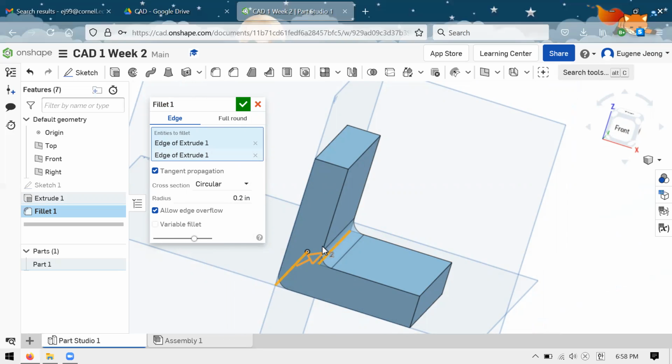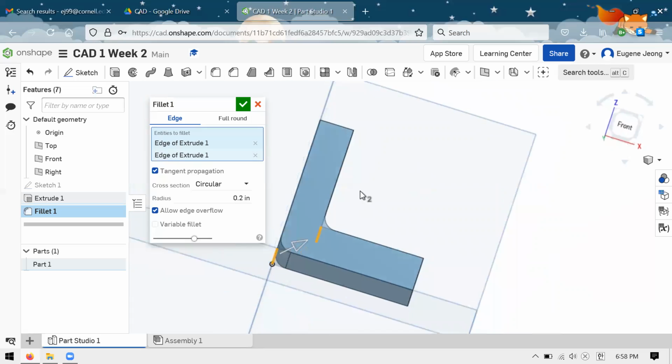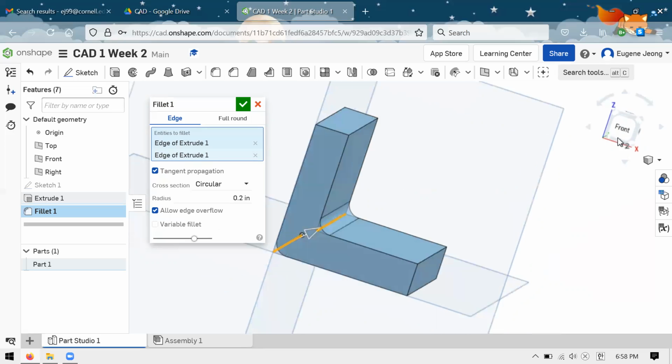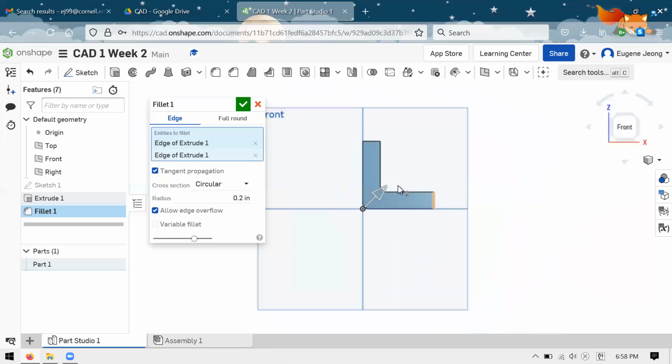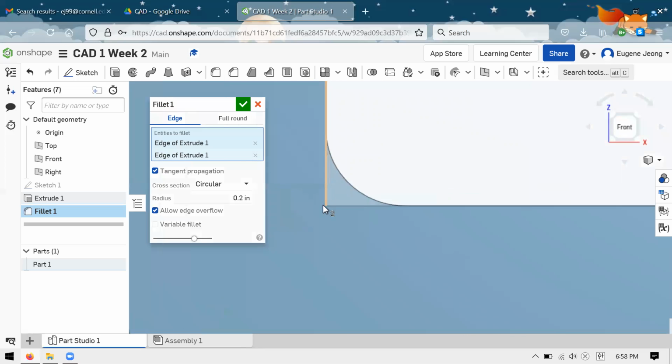I'm not too familiar with how most of you on your teams manufacture most of your robot parts. Maybe there's some that you get machined. Maybe some of it is 3D printing. And so there are always minimum radius requirements for making parts on a machine. It'll vary based on what the machine is, what the process is, but just due to the limitations of the hardware itself, it's not possible to make an infinitely sharp corner like this ideal square that's modeled here.